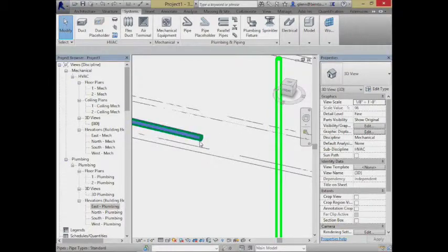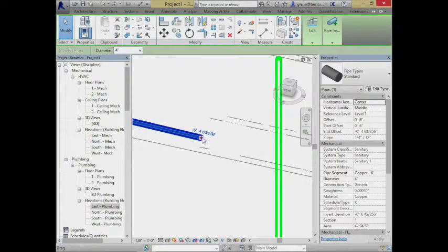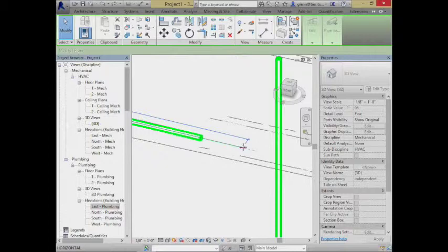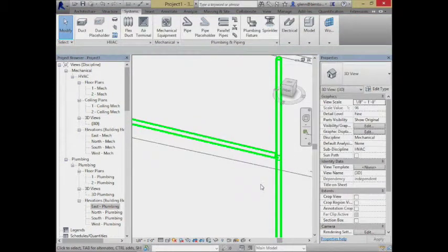They're looking okay. If I click on this one and grab the little handle, as soon as I get the two to intersect, it'll try to join them in there. And it will, if it thinks there's any physical way to do that. Ways that doesn't work, ways you can go wrong: if you have another intersection that happens to be hitting it at almost exactly the same point so that it couldn't put both connections in, it'll complain and say, I can't route that. It has to be something that it thinks it can physically do.